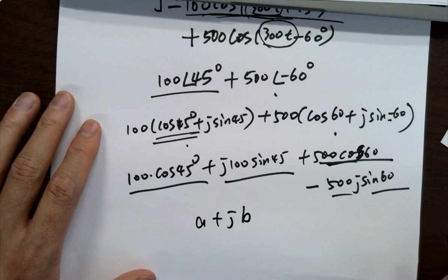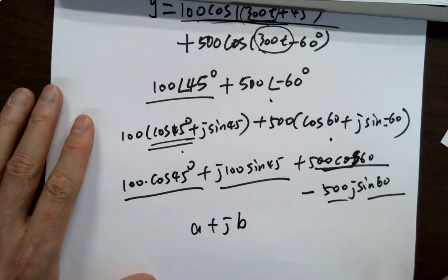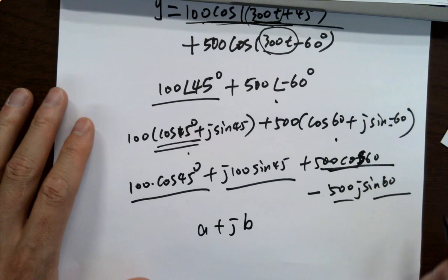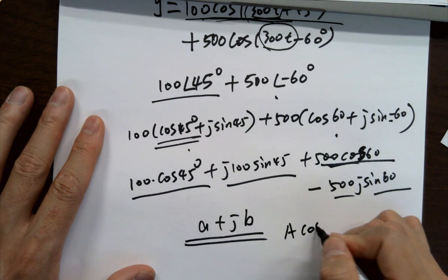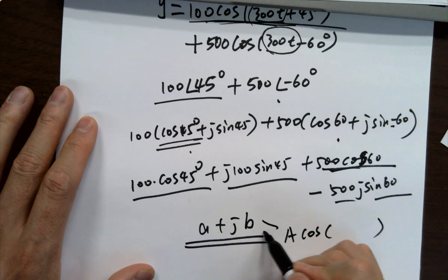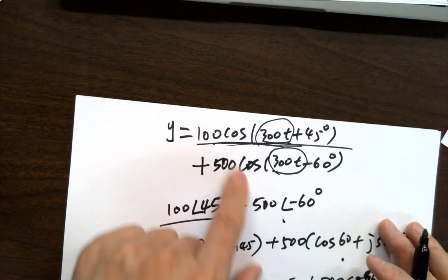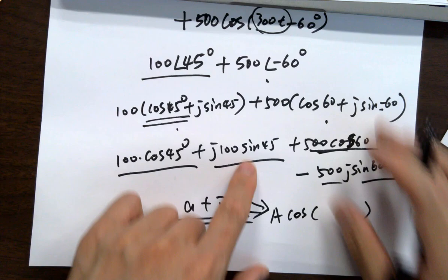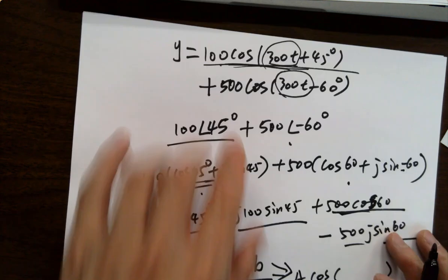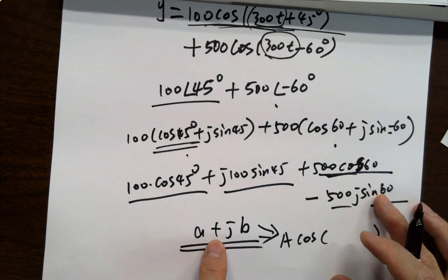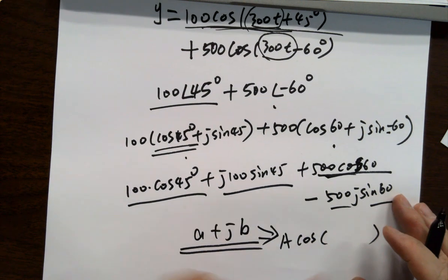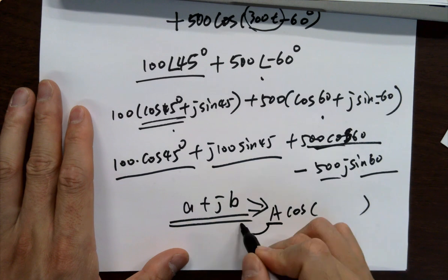Okay. 327 minus 362j. How do you recover this? Convert it to cosine of something. How? Because it's asking to combine these two time domain signals, eventually you are getting a time domain signal. Now we combine them in the phasor domain, and we got this rectangular form. Now we just need to get back here. So what is A from here?